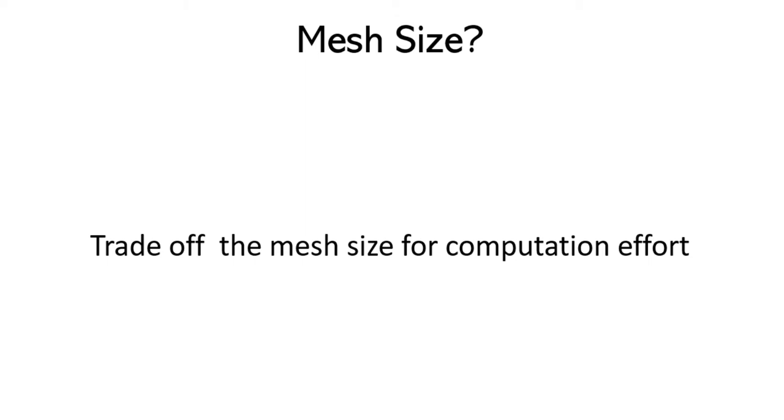There is no hard and fast rule to give you the exact number at which you need to stop meshing and pick the result. That all depends on your experience. While you perform the meshing, the internal nodes are created. The more internal nodes are created, the better the result can be expected. But at the same time, your computational effort also gets magnified. You need to invest a lot of man hours. You need to stress your computer because it will consume a huge amount of computer resources like RAM and processing speed. So you need to strike the balance between the result that you are getting and the density of mesh that you can afford in your structure.